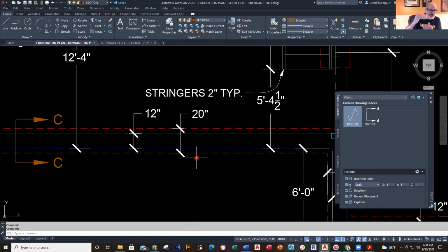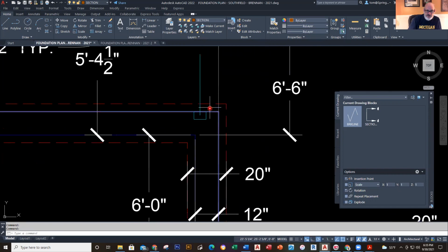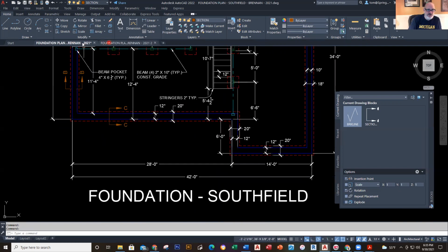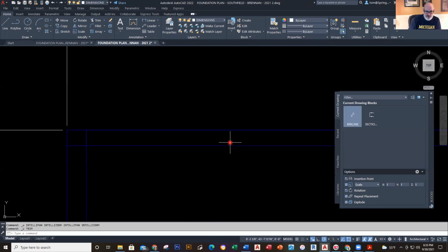If that's a 12-inch. Professor, my fillet command doesn't work. Your fillet command doesn't work. You mean out here to do the corner? Yeah. Okay, let me show you how you use the fillet command to make those connect. So if these don't connect, let's go ahead and back this out here.